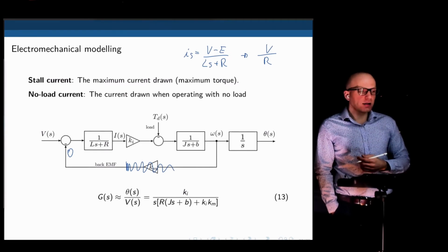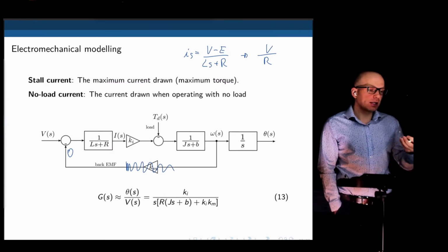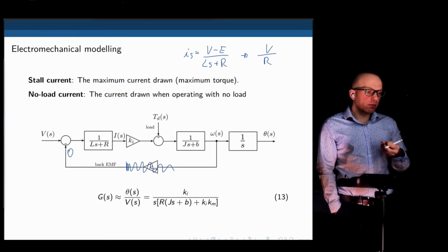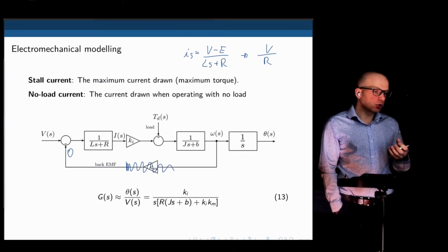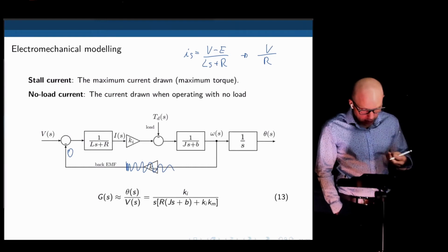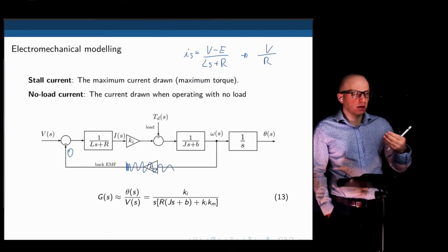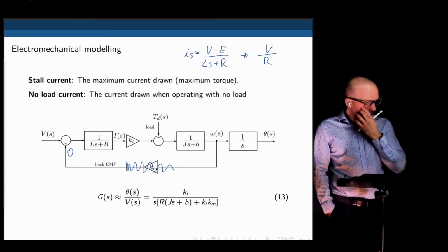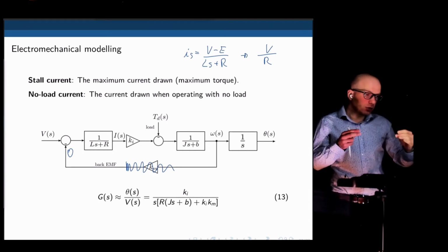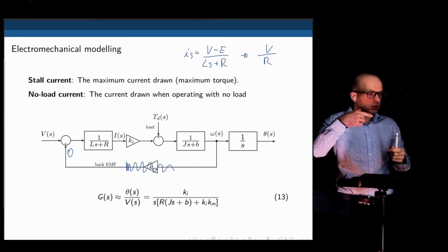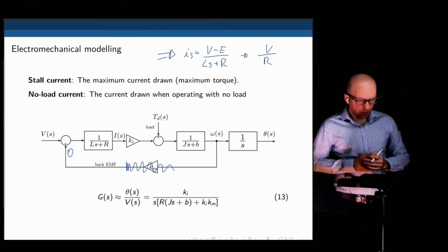Multiply that by Ki, that gives you the no load, or the stall, gives you the stall torque, the torque at no speed. That torque cannot be sustained for a long period of time because it will simply burn the coils. It's not designed to handle that amount of current. But it only occurs when the motor has no speed. It's at rest. And that's exactly why when you turn on a motor, you see a spike in a current and then it slowly decreases, because then the back EMF, as it starts to rotate, kicks in, and then this relation here will make the current drop.